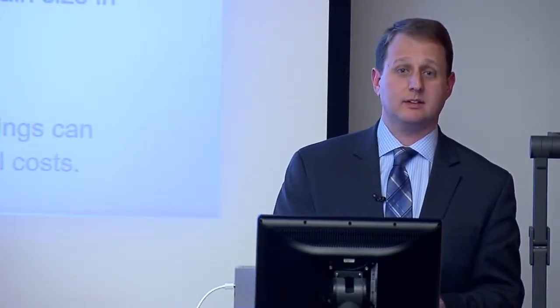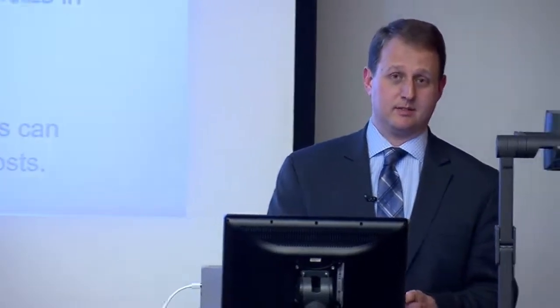See, there were some more student questions in the back. Speaking more to the engineering side, tungsten is much more expensive than chromium. Does the lifetime performance on the parts outweigh the costs? Great question. The things I've shown you are all technical successes, but they are of mixed market success, and there are many more like them. This is not a general chrome replacement for the reason you suggest. There are many market niches where selling on increased lifetime doesn't work, because the person buying doesn't see the value many years out. So a lot of applications have died on the vine because this is definitely more expensive than chromium. It's very dependent on the application. In the case of the bumpers, if I remember correctly, there was about a 5 to 10% cost premium, but a doubling in lifetime. In some economies and to some customers that can sell, but to others it can't.